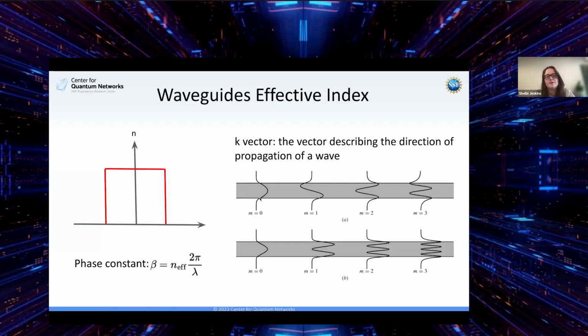These are examples of different modes, TE and TM modes. This is the first order mode, where you can see this is the N2 material, this is N1, N3, N2. Most of the light here is confined within the mode. There's one peak. For the second order mode, which is M1, confusingly enough, there are arms here that are not confined within the core of the material, but this is just to say you can have higher and higher modes propagate if you have geometry and materials that support that.